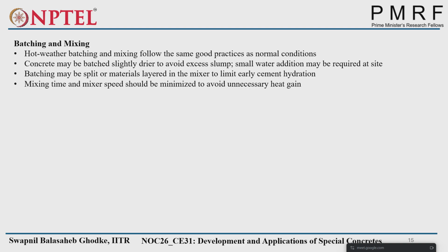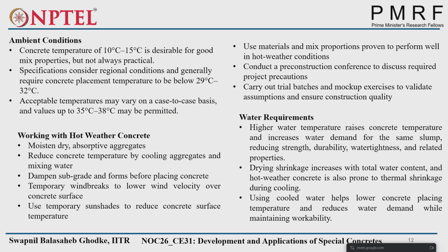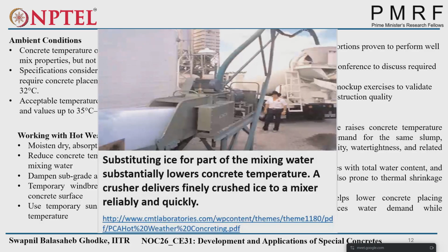According to the latent heat aspect, it may be correct. But if you want to utilize the whole cement hydration process, it will not be good. In the lecture itself, sir has explained why we have to use crushed ice, and you can see it in the last slide. They are not using complete ice blocks, because if you put ice directly, certain water will melt and start hydration.